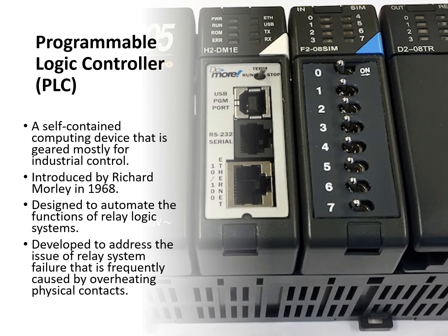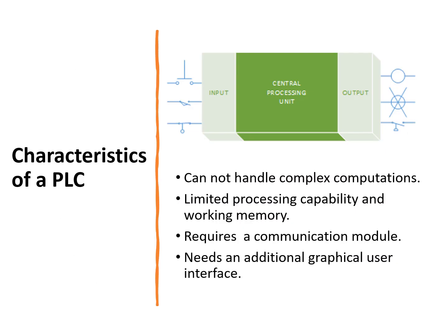Further, the ease of customizing the functionality of a PLC through programming and its modularity makes it conducive to widespread deployment. Despite the proven merits of PLCs, they do have disadvantages. Unlike computers, they cannot handle complex computations due to a limited central processing unit, CPU, and a small working memory. In addition, they require interface modules for communication and graphical display.